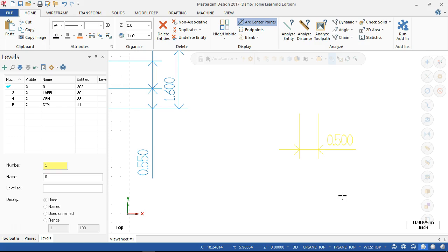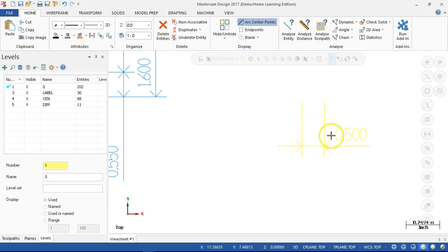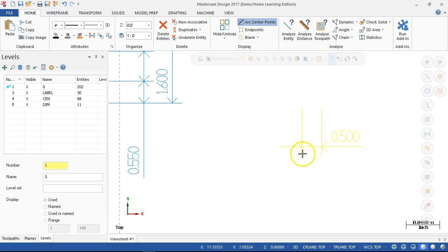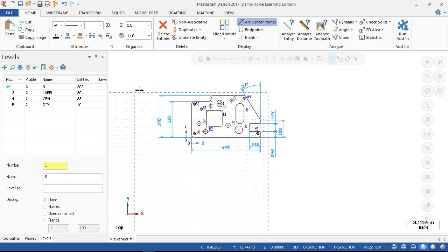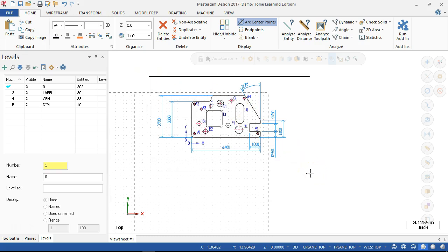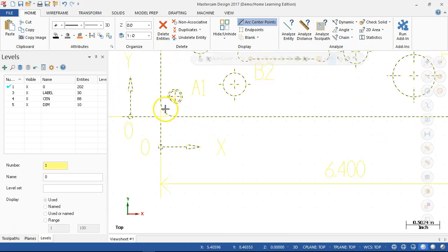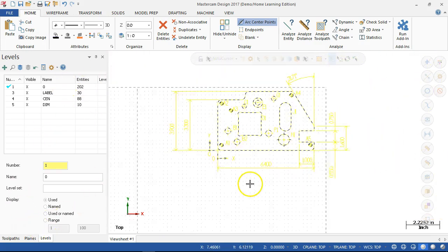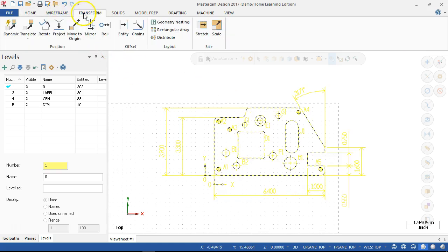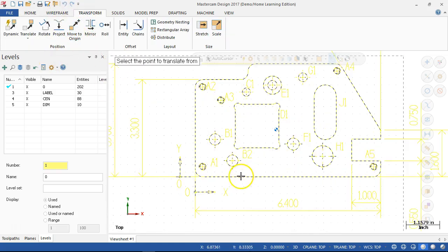Sometimes we'd want to watch out for any type of explode where that is 1, 2, 3, 4, 5, 6, 10, 15 just separate entities, and based on this, would have to go through and make the selection for each one. So I do want to move all of this at once. For our example, I'm not overly concerned with our position. So where this ended up, let's go into the transform, and we're going to move to origin.